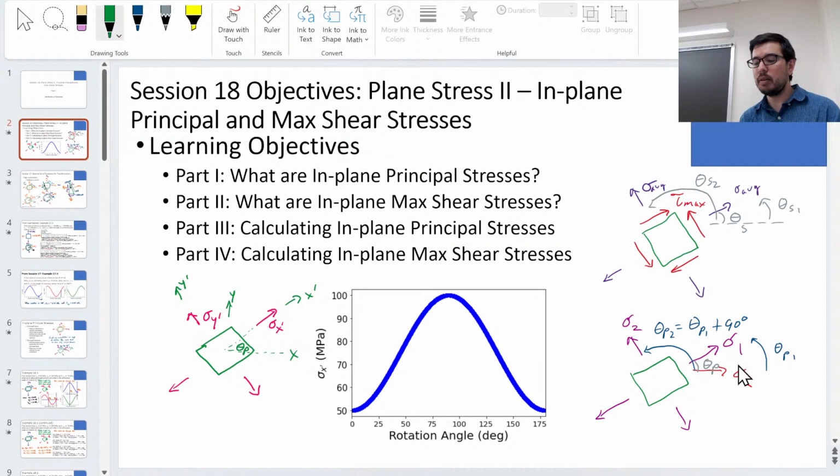More carefully said, sigma 1 and sigma 2 are when tau is equal to 0, because you could have a sigma 1 that could be less and sigma 2 could be a little bit more. So I should be careful, but it's the state where there's no shear stress. That's what in-plane principal stresses are getting at, and a sigma 1 should be a max. All right. Thank you for asking that clarifying question.